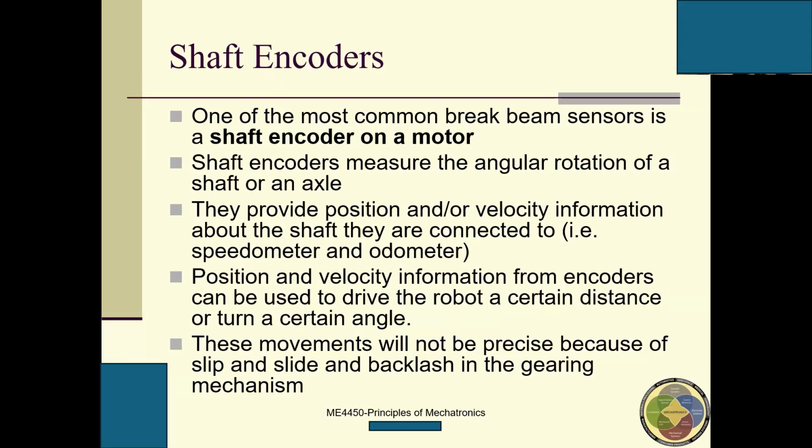Backlash is the result of manufacturing inefficiency. These are two gears, and they are not meeting precisely. There's some clearance on one end. If you turn in the opposite direction, you need to compensate for this clearance first. That's backlash. You understand, Sarah?